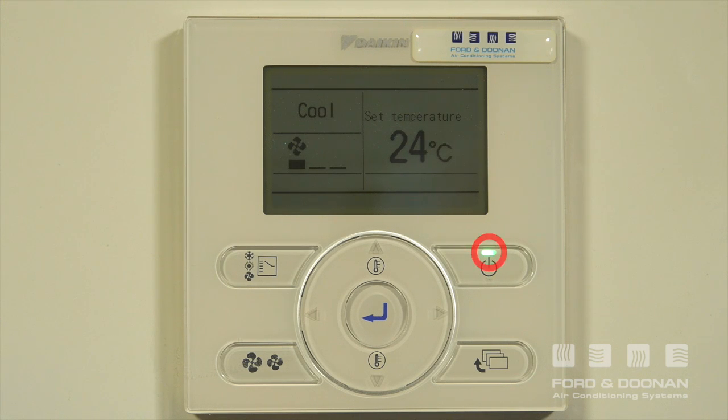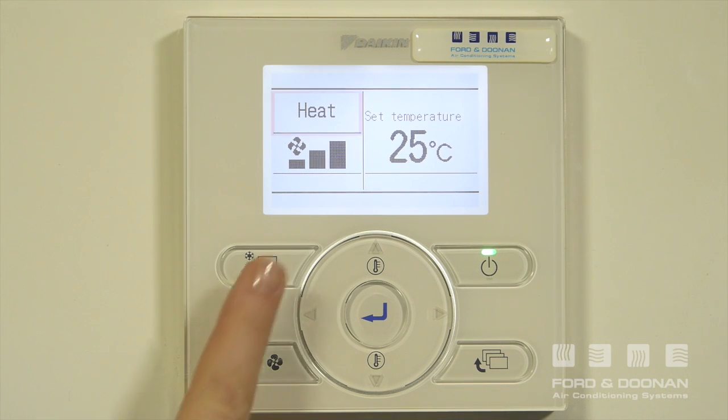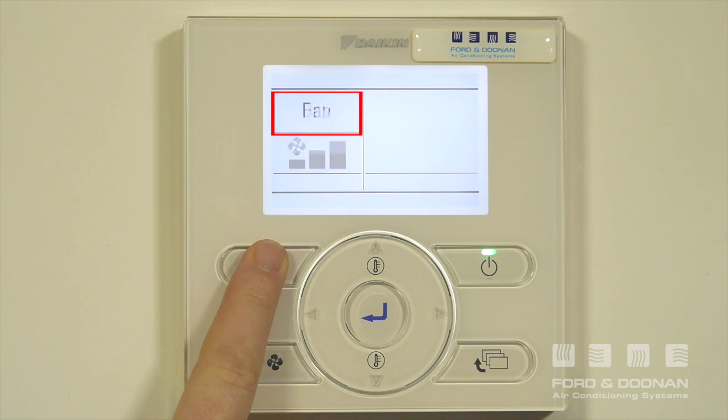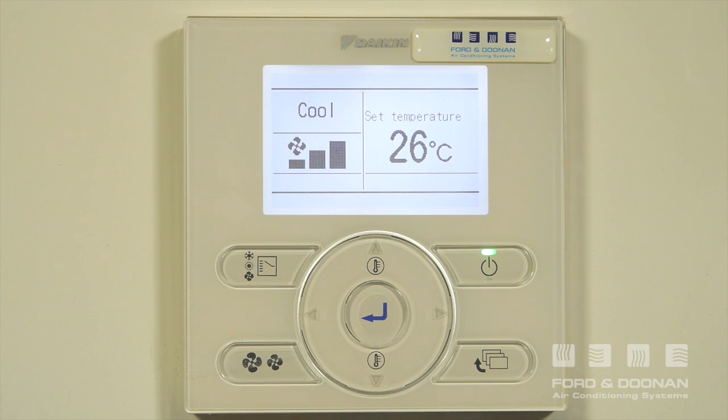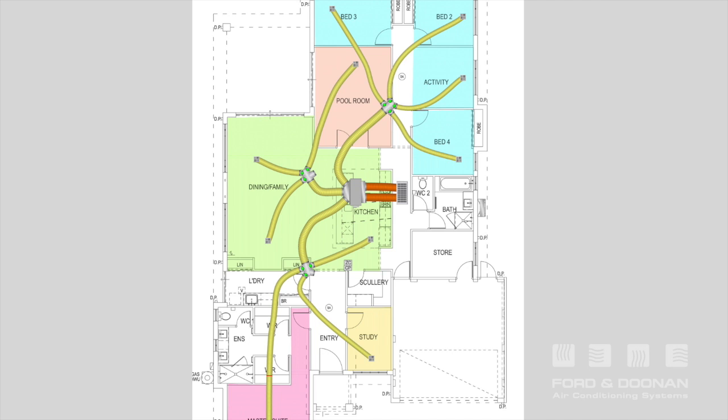Once your air conditioner has been activated, you'll be able to turn it on using the big on button. Now, set the appropriate mode required. Make sure you have the correct icon showing on your controller. Once your desired mode is selected, either cooling or heating, you can adjust the temperature to suit. For maximum efficiency and optimum energy consumption, we recommend setting the cooling cycle to 24 degrees and the heating cycle to 21 degrees.